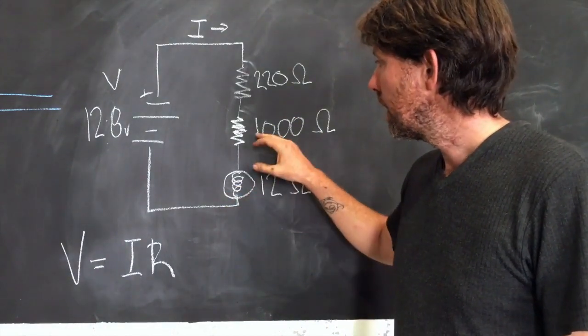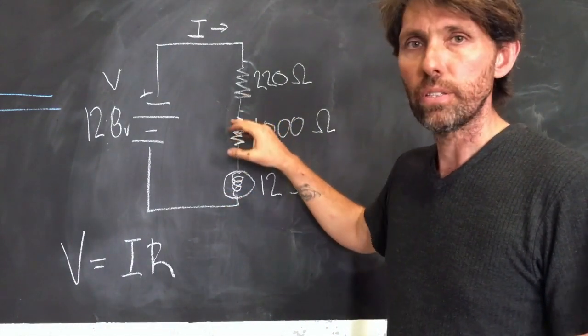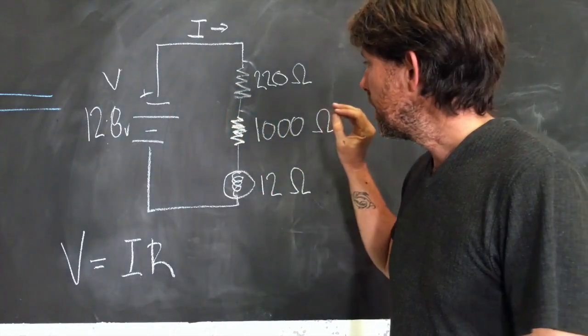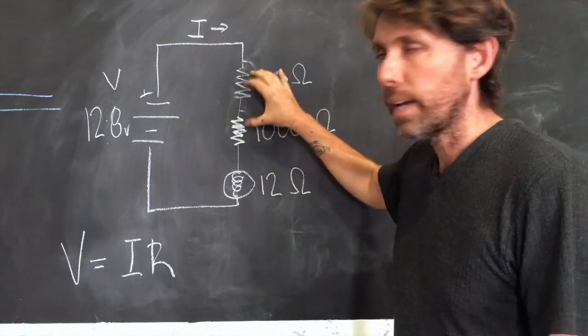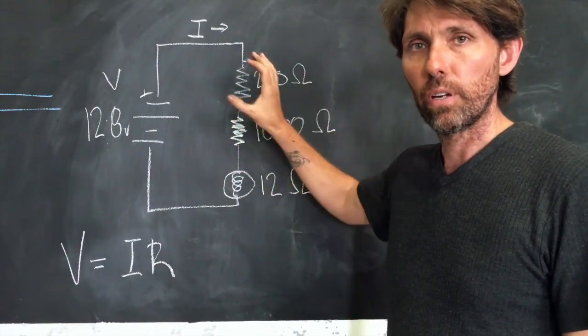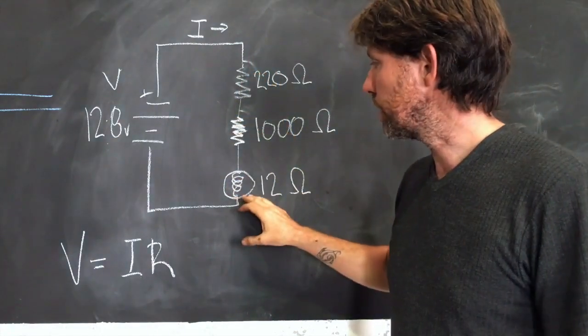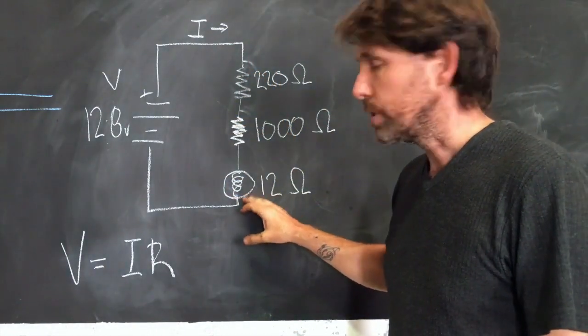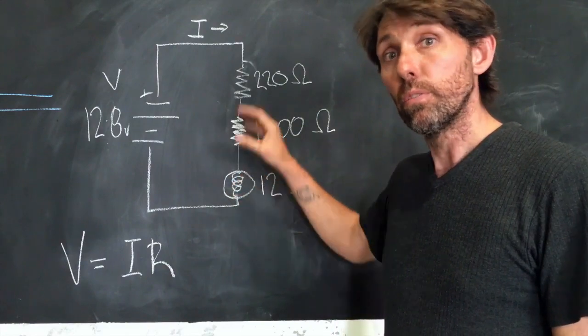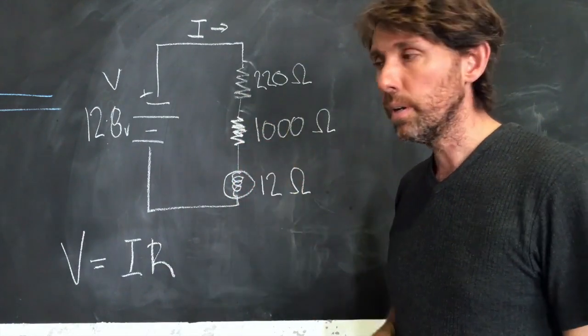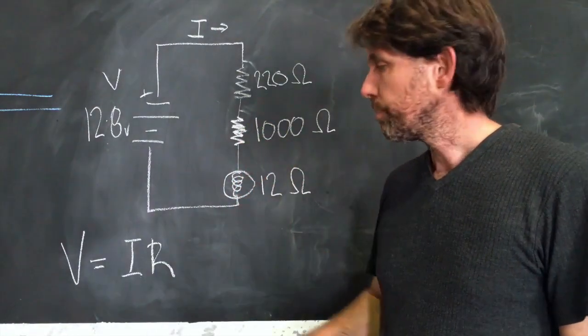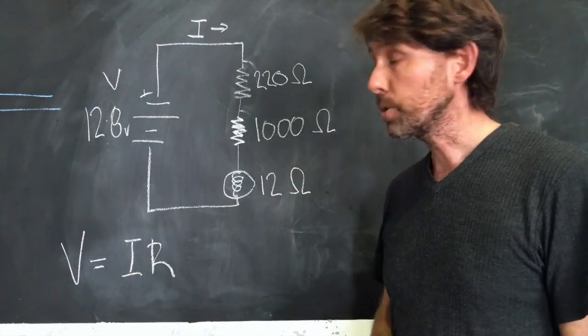And what that means is that if you get a bad connection that's giving you a high resistance, then that connection is going to consume by far the lion's share of the voltage, and the device will actually get very little. High resistance devices are a little bit more immune to voltage drop because it all works in proportion. There's no absolutes to this, and the formula is all about figuring out those proportions.